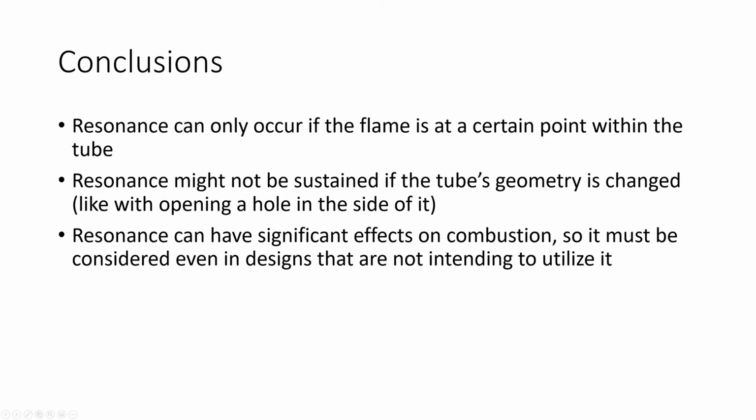Several important takeaways can be had from this lab. Resonance seems to only occur when the flame is at certain points, meaning resonance is dependent not only on the geometry of the resonant cavity, but also the characteristics of the energy source. Geometry does have an effect though, as opening a hole causes resonance to completely cease. Finally, resonance can significantly impact the intensity of combustion, so it must be taken into account even in designs that do not intend to have any resonance to avoid overstressing the structure.